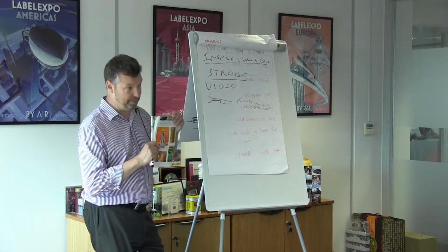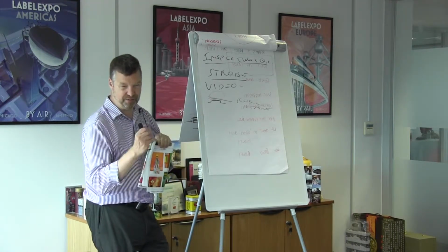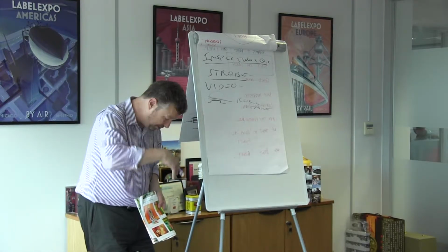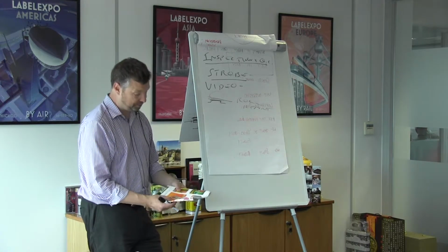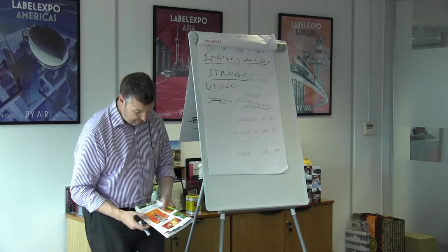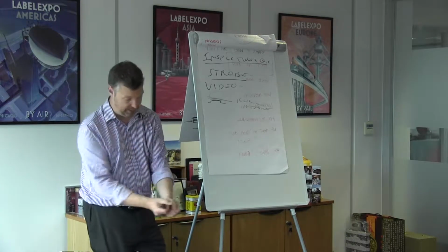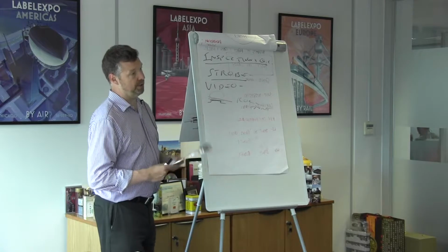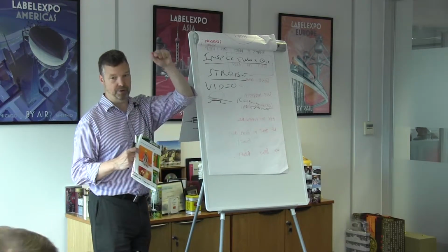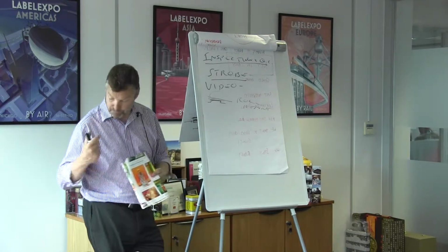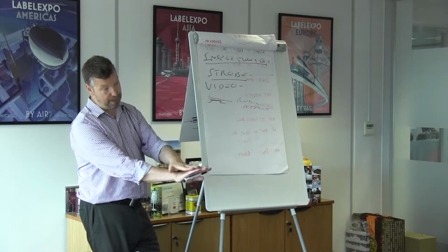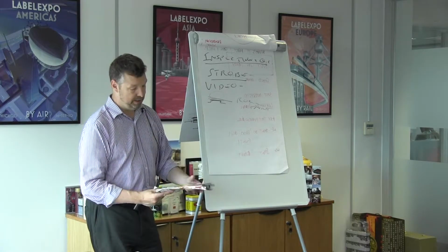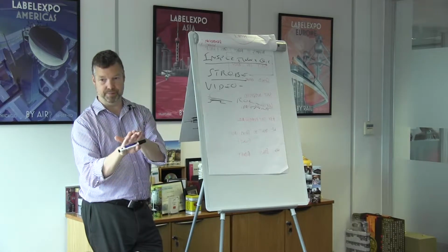is, into their inspection camera, they build a thing called a spectrophotometer, and we might have touched on this briefly earlier when we did the color. So what a spectrophotometer does is it basically bounces light onto an image, and what comes back, reflected back, it captures as the color reference. So what it knows is that orange there, if you take a Pantone book, is exactly that orange. You can give it a number and a name. So a spectrophotometer can say that color should be exactly this orange, and that color should be exactly that orange. It's measuring the color that's bouncing back off that image. And it's already gone to the proof and done exactly the same thing. It's bounced the color off the proof and said, right, that is exactly that shade of orange that we're looking for.